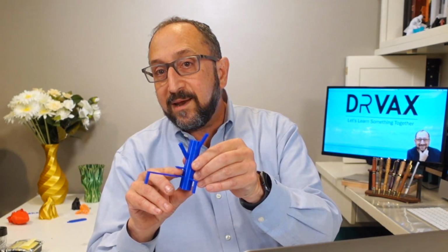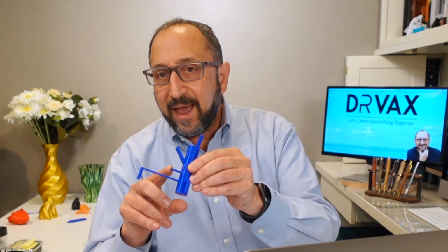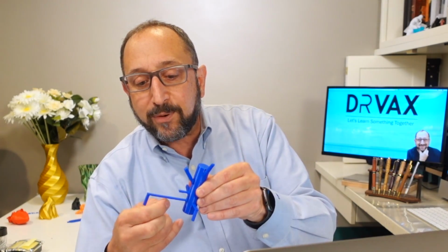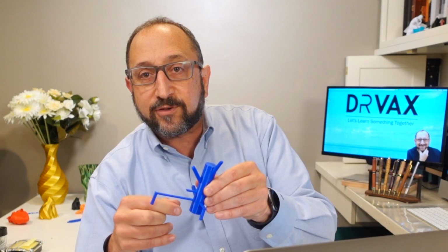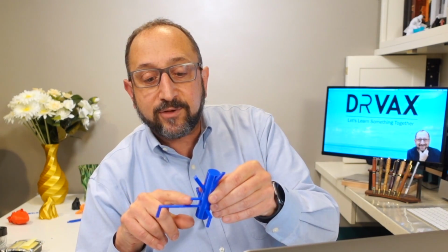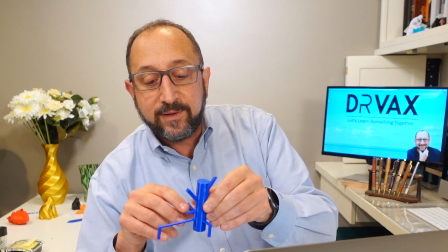And this one right here has a little bit of a droop in it. And why is that? Because when I printed this, I only added supports to the build plate. So there was no support under here, so it did droop a little bit, but you'll be able to print very successful prints. Thanks for watching.